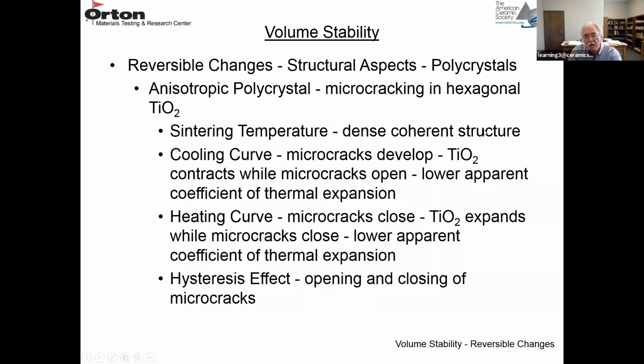So at the sintering temperature, you have a dense coherent structure. When you cool it, microcracks develop. The TiO2 material contracts while the microcracks open. You have this lower apparent coefficient of thermal expansion.